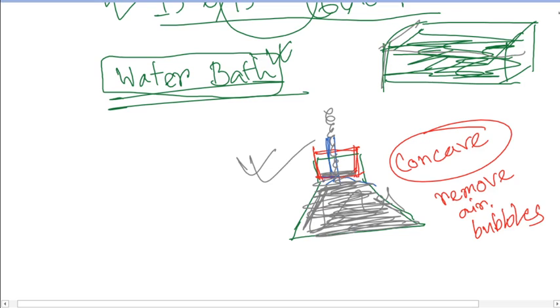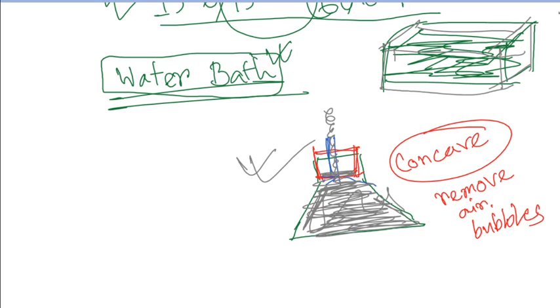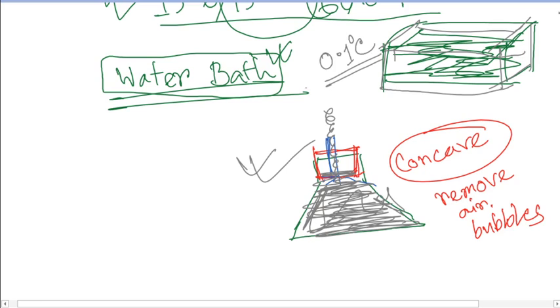We have said this is the water bath. We need to prepare it according to our requirement. The required temperature will have to be maintained in this water bath, according to the ASTM designation, within the given range. A 0.1 degree centigrade deviation of the desired temperature is allowed.